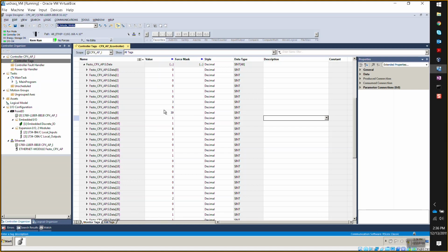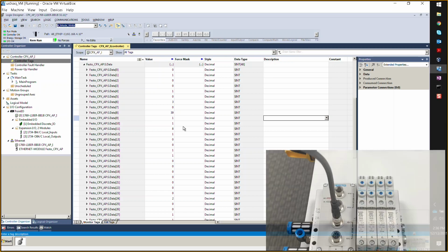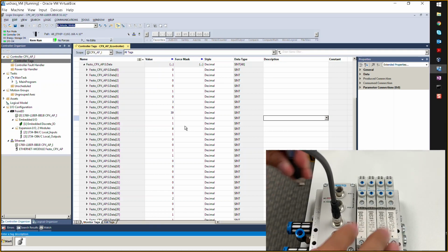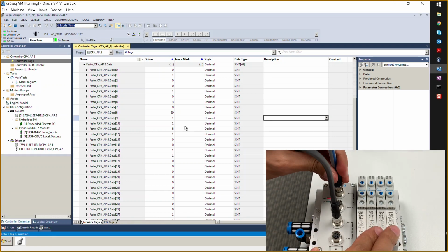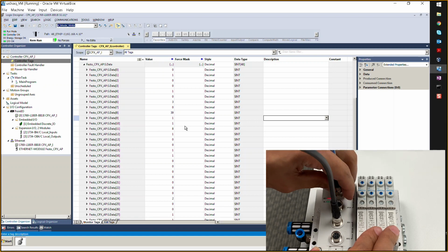Okay. So now that we were able to see some errors here, this particular error, to recover from this in this native format, you have to recycle the power to the API. So maybe you could reconnect the cable. Okay, I reconnected the cable, and it won't correct itself, heal itself. You'd have to recycle the power in this case. Okay, so let me recycle the power to the whole API network.